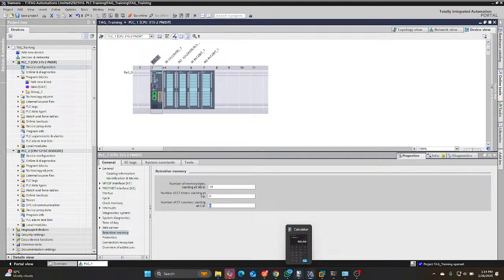We are starting manual start and stop. Okay? Start on manual, stop on manual. So we have dry run, that is the sensor, and we have auto mode. It's on auto mode, waiting for the auto command. The manual mode is waiting for the manual command. And there are different states. How it will respond on HMI when running on manual is different from when they are running on auto mode. What does that mean?